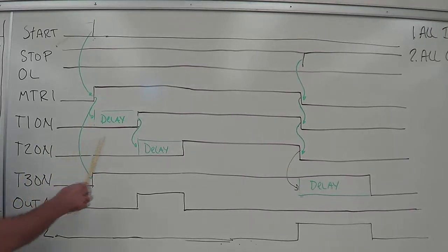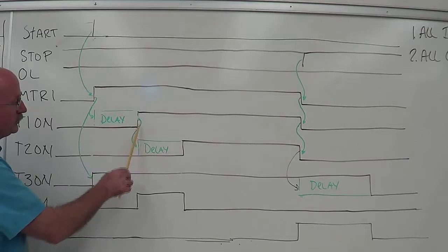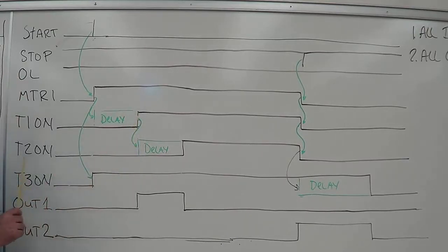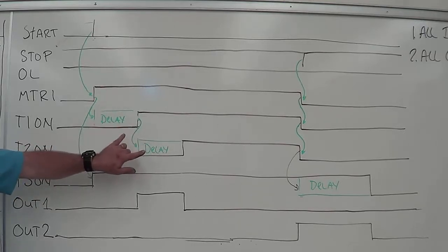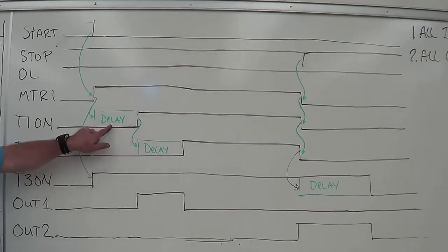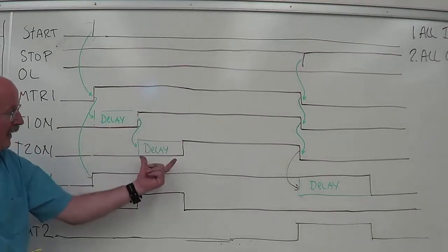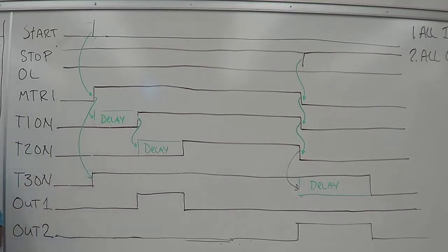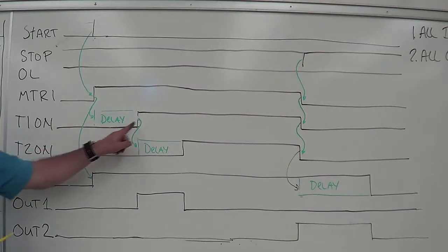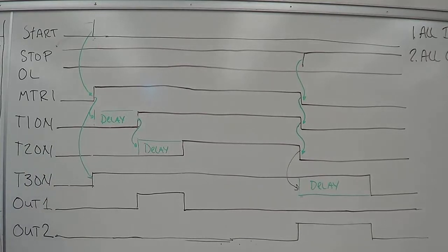You notice I do not have the delay set up over here. This delay will start when that output turns on. There's a question of why I don't just have a 10-second delay here and a 20-second delay here. If those things are supposed to be independent of each other, and I change this to, say, 15 seconds, that will push it over here, and I'll lose my 10-second difference in there. You'll have to sit there and make sure you adjust all the numbers. It's easier to have this triggering that, so they become independent of each other.